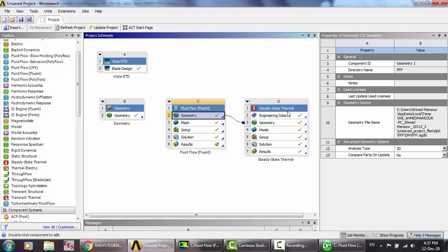If you wanna use the heat flux plus convection, you have to use the solar load, and I uploaded another video, a previous video, on how to use the solar ray tracing. This is the only case I know so far to use the heat flux to hit the surface plus adding convection.